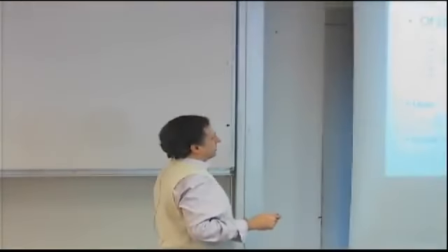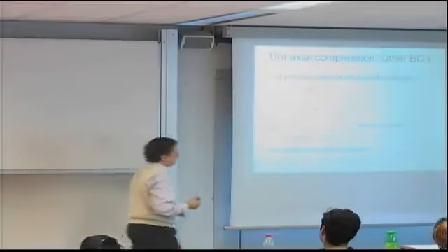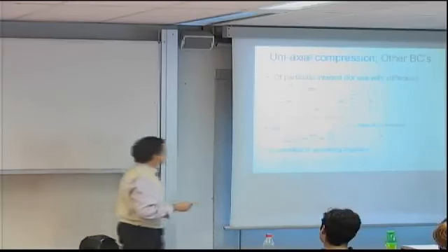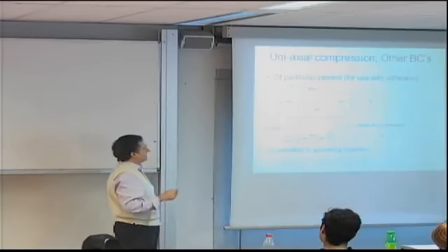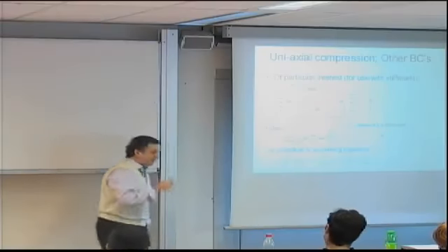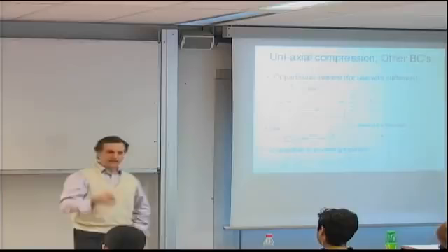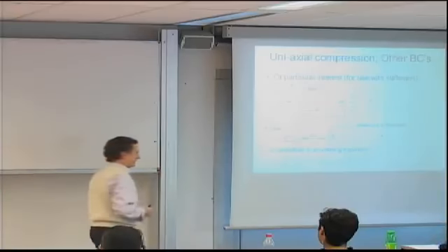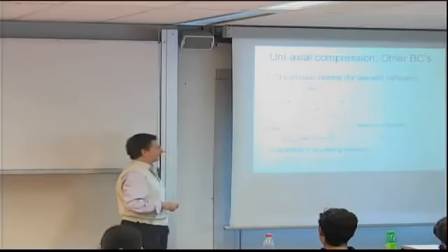And we now are in trouble because we need some solution, some W expression that will account for the boundary condition which says this has to be 0. The loads there are 0 and the displacement there is free. It can be whatever ends up being from the solution of the problem.